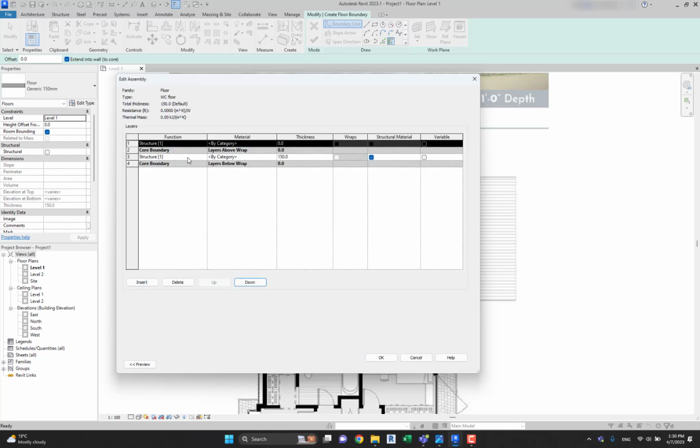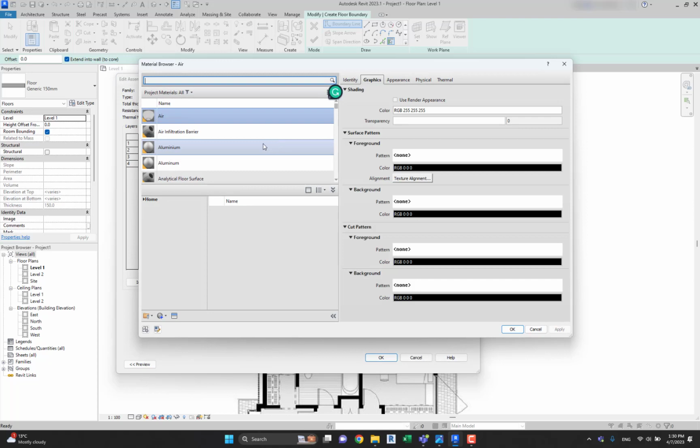I'm not concerned about the material of the structure because I'm gonna create the plan views and the structural material will not be visible at these plan views, so I'm not concerned about it. In reality, you probably create additional different layers, but at this moment we're just creating an architectural model. Yeah, so let's create only one additional layer, which is gonna be like flooring. Let's change the function and let's change its material.